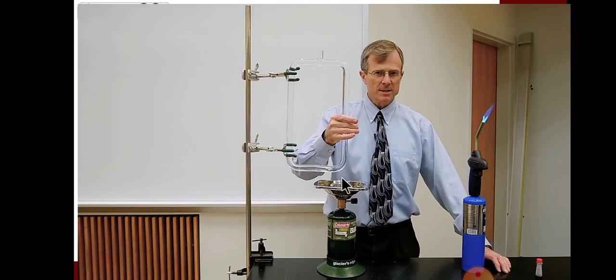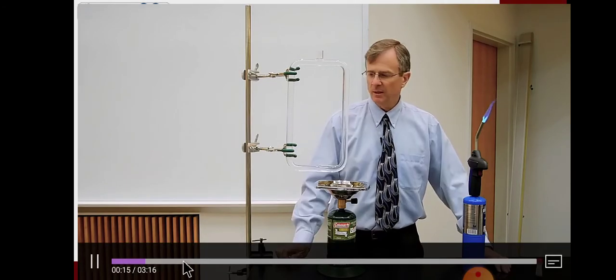When we heat it, or light the stove over here, a natural flow starts from this side, because if we heat the plate at this point, the liquid at this point becomes heated and expands. Due to the expansion its density becomes lower, so it moves upward. When it moves upward there will be a bend, so it moves like this and like this. This liquid moves above, so other liquid takes its place, and it also moves upward. So a natural flow starts like this. Let's play the video.